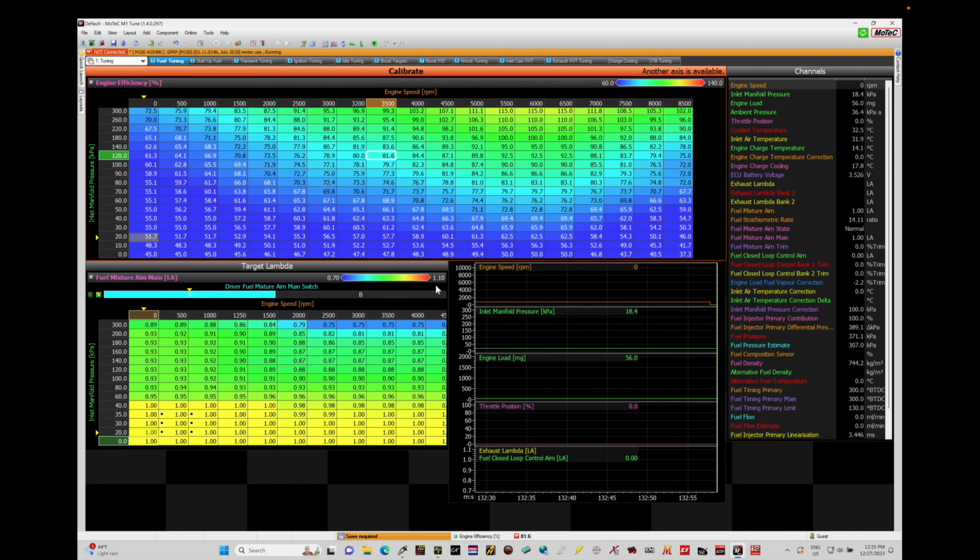And then we'll also be able to reference this a little bit better conceptually when we are programming and calibrating with the Motec, understanding if we have an error on the fuel modeling side or on the airflow modeling side when we're dialing in everything in terms of our fueling to our engine, utilizing something like our volumetric efficiency table. So let's jump in here and take a look at a couple concepts.